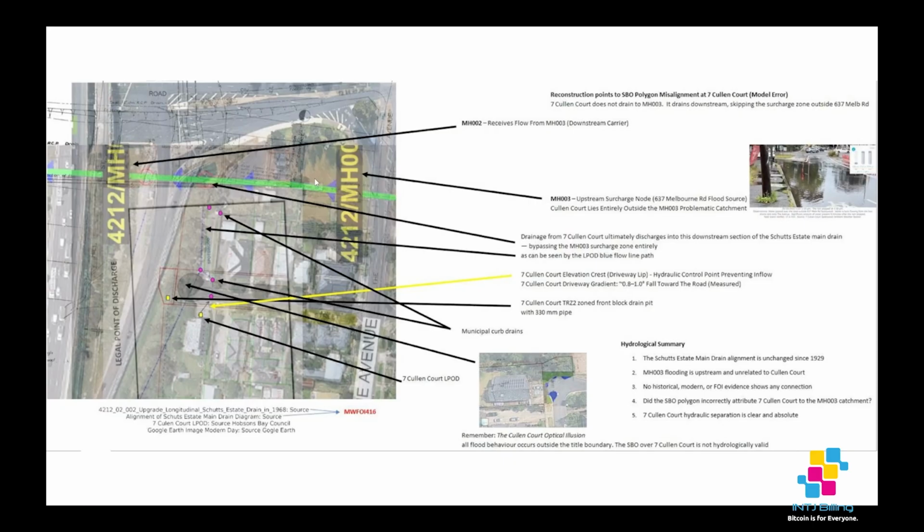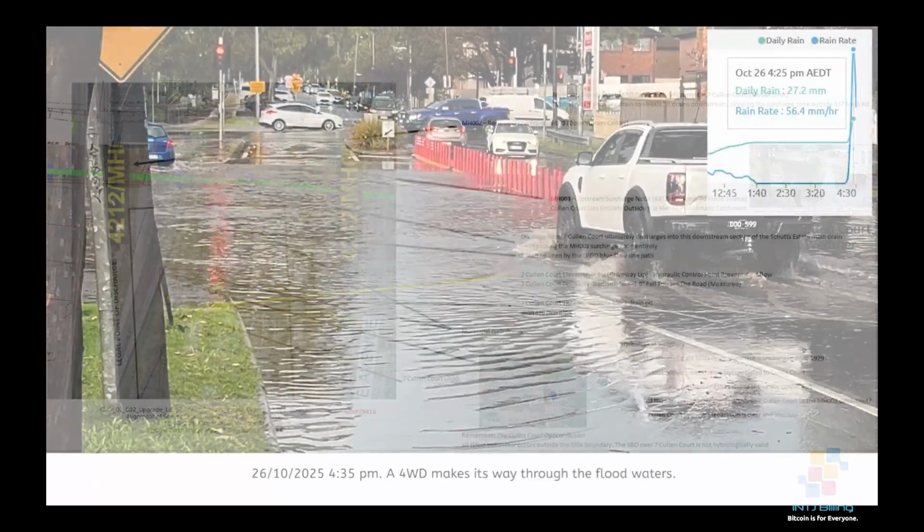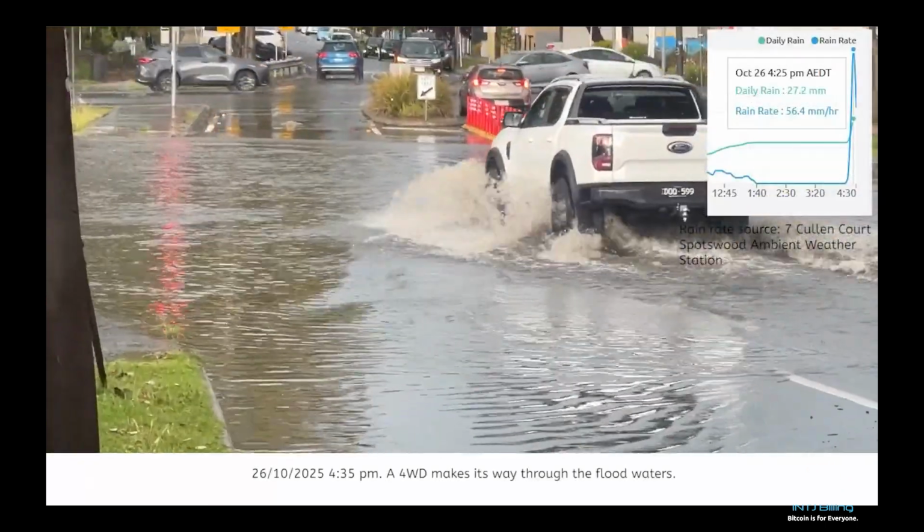All right, so let's go through this. This reconstruction that I've created here points to an SBO polygon misalignment at 7 Cullen Court. So a modelling error, basically. What you'll notice with this image is that 7 Cullen Court, which is here, does not drain to MH003. So MH003 is our problematic node, which is the cause of all the flooding outside 637 Melbourne Road.